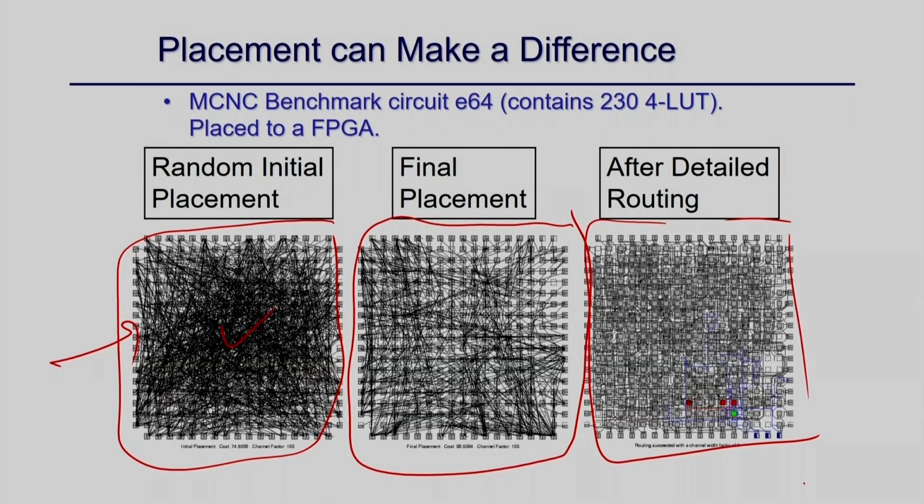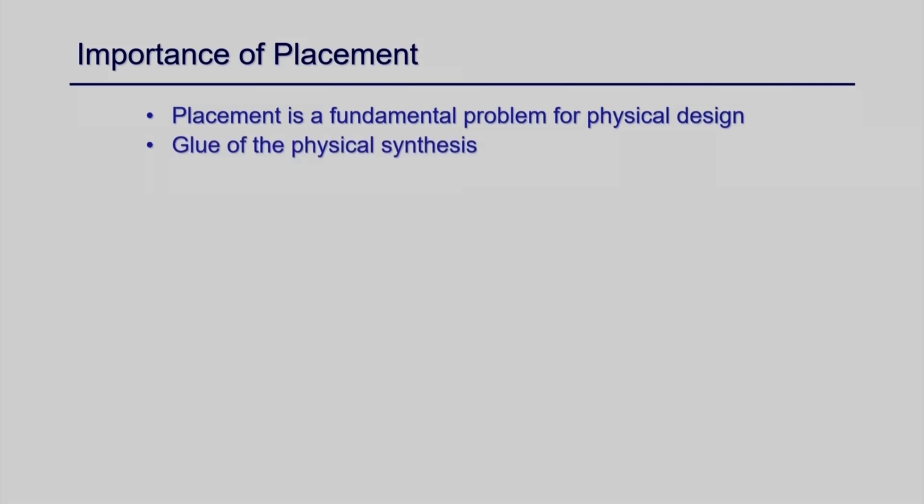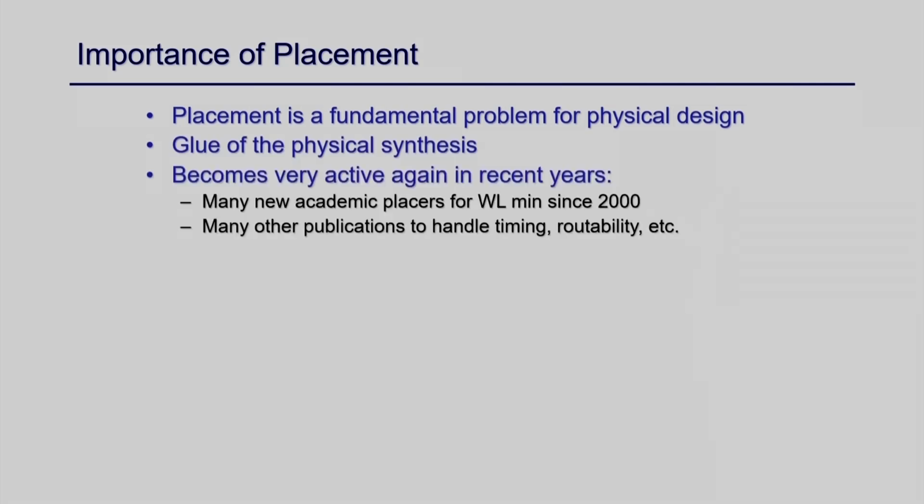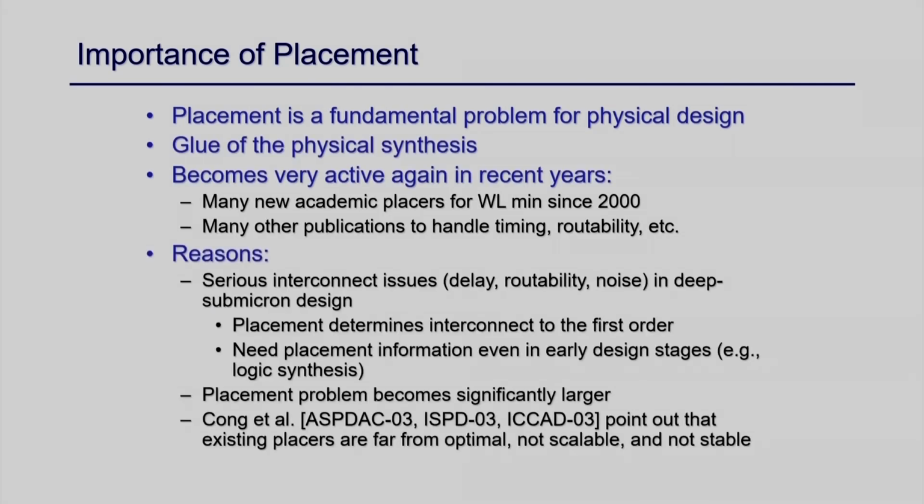So you can see that you can actually make a lot of interconnections less just by moving your blocks during placement. So placement has a huge impact on the final route interconnection cost. As I mentioned, the route interconnection cost is growing more day by day, so placement becomes important just to reduce the total interconnection cost.